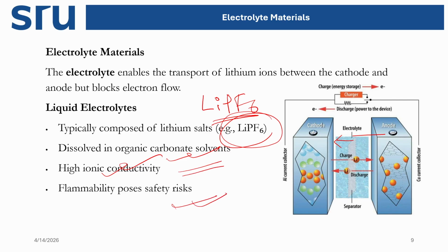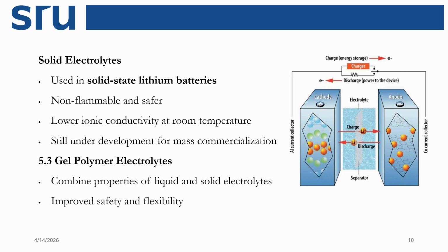The disadvantage of the liquid electrolyte is that it can catch fire very easily. If you use a solid electrolyte, the advantage is that the leakage problem or fire problem will be restricted or reduced. But the ionic conductivity of the material is very low, so the performance decreases.